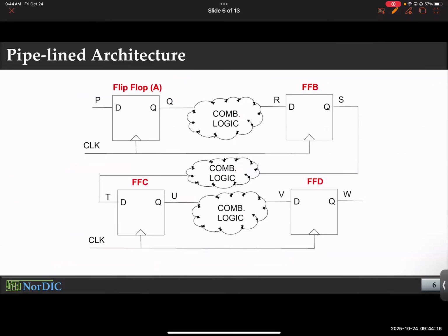Okay, now, this is the grand vision. Super simple cartoonish representation of the grand vision of computer hardware. Here is how different types of logics are designed across large systems. You have combinational logic that doesn't care about the history. You have sequential logic where history is basically the king. So here is how you design the overall system. You have combinational logic. It could be an adder, it could be a multiplier, it could be something even more complicated. And before and after, you have flip-flops.